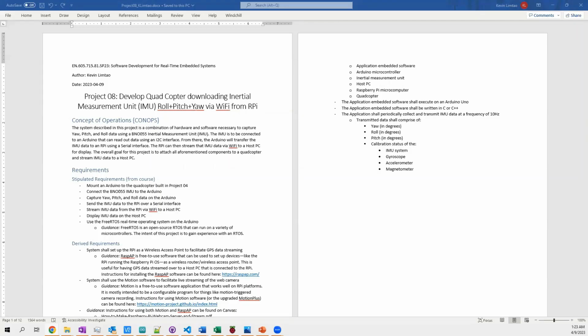Hi, everyone. This is Kevin Limtow here to describe my Project 8 report, wherein we are creating a combination of hardware and software to capture yaw, pitch, and roll data. That's going to be using a BNO055 IMU, which is kindly provided by our professor. So that IMU is going to be connected to, in my case, an Arduino Uno, but it could really be any Arduino that can read out data from that IMU using its built-in I2C interface.